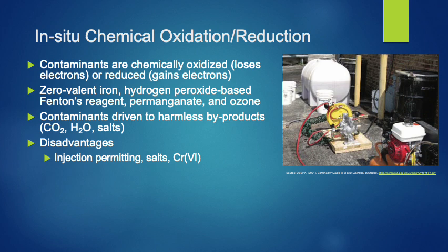The approach works well in both saturated and unsaturated soil and can address a wide variety of contaminants in a wide variety of soils. However, it's very important to know what chemical reactions will take place because in some instances, harmful byproducts can be generated. Additionally, you are injecting reagents into the subsurface, so injection permitting with public agencies is a necessary task.